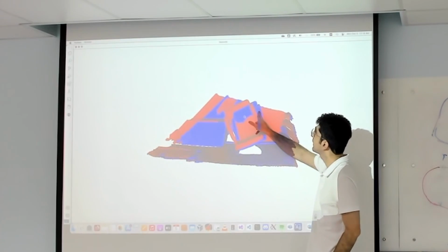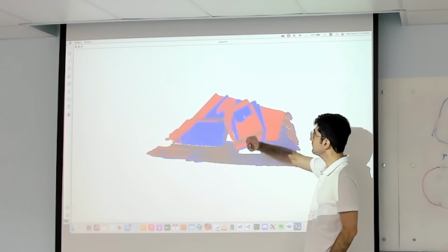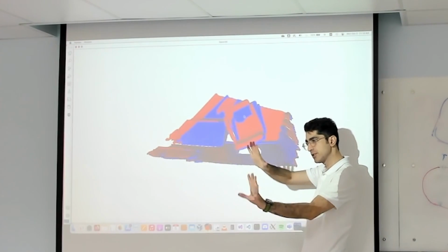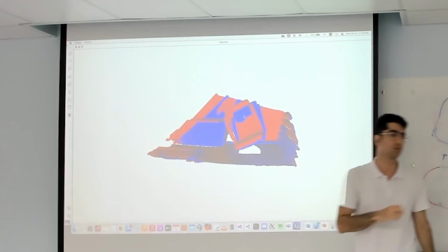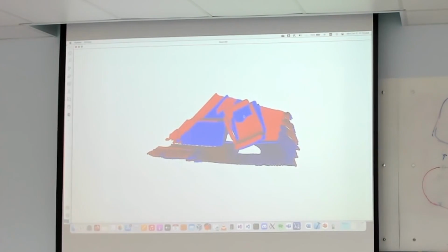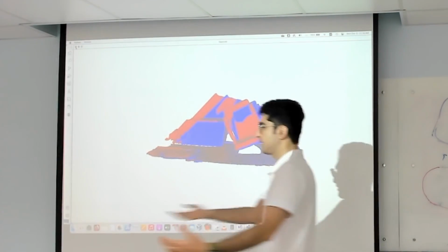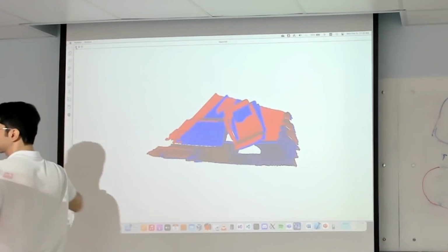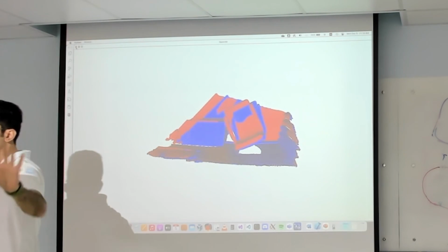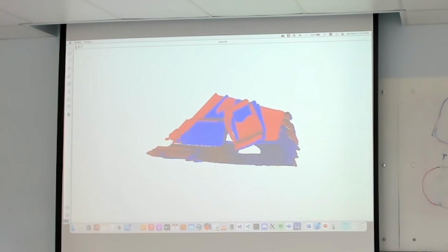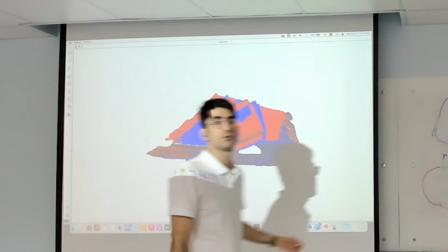But yeah, you can see that after applying some iterations, it came closer. And if we continue iterations with good thresholding, we can achieve highly accurate point cloud matching, so that your robot is moving, scanning the environment. Every time one of these comes, you have one as reference, the map that you have. New one comes, you merge it. New one comes, you merge it. New one comes, you merge it. Then you can construct the map of the environment in 3D.